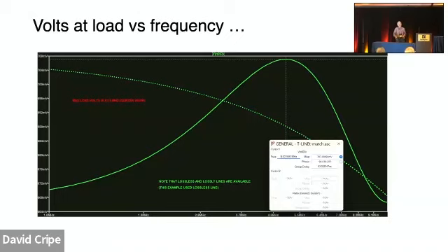There are other interesting things you can play with here, just for fun or education. This is a sine wave, of course, because I'm doing AC analysis. You can go into transient analysis. You can launch little nanosecond wide pulses, and if you're not matched on the far end, you can see them coming back. Now, you can't probe inside that transmission line, but you can make one out of several transmission lines. You can look at those points, and it's fun to see that on the graph. It went this way, now it's come back this way. It's shorter.